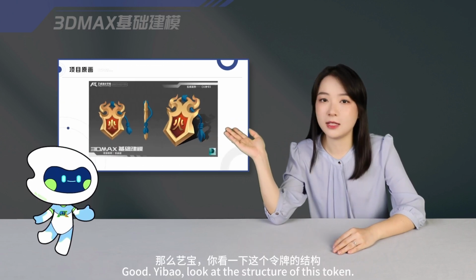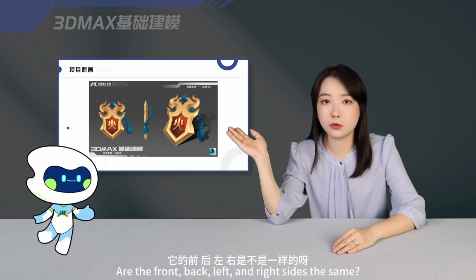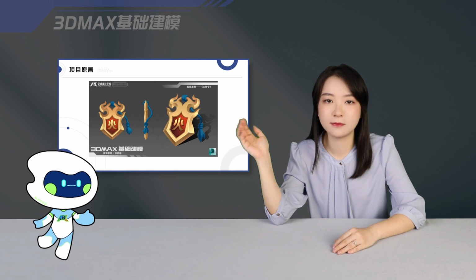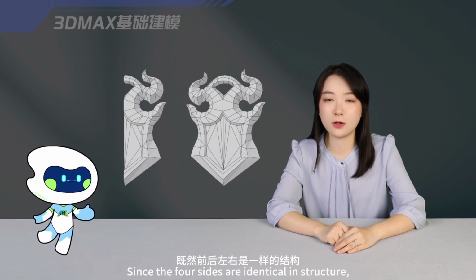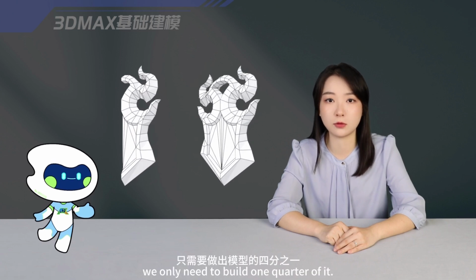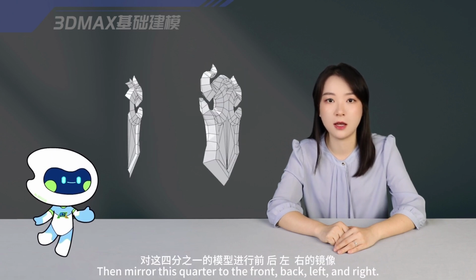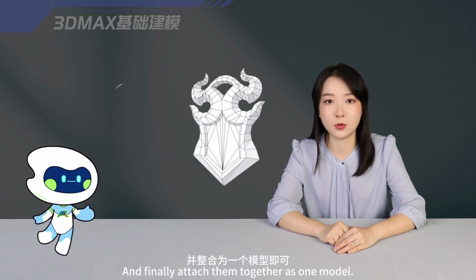Good. Yibao, look at the structure of this token. Are the front, back, left, and right sides the same? Teacher, yes, they are. Since the 4 sides are identical in structure, when creating the model, we only need to build 1/4 of it, then mirror this quarter to the front, back, left, and right, and finally attach them together as one model.